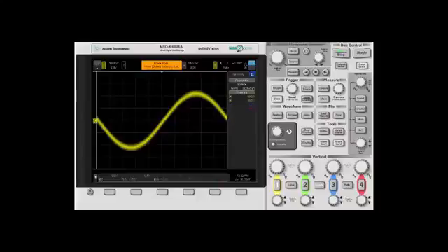As mentioned in the example, one of the benefits of using a bandwidth limit filter on your channel is that it will help improve the accuracy of your low power measurement. In this exercise, we will see how the accuracy of the variance of amplitude changes once a filter is applied. I will demonstrate this by using a very noisy sine wave, which can be found in the training signals on your Keysight oscilloscope. We can use our histogram function in order to view the variance of our amplitude.